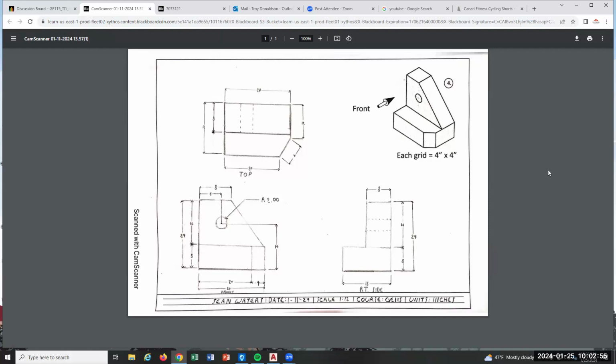How's it look? It's okay. It's got some dimensions around it. Is there anything wrong that you see here? It doesn't line up. What's that called again? I know, it's a big word. Starts with a P. Projection. Thank you. It's not in projection. So remember that the left side of the front view should line up with the left side of the top view. That's called projection. In AutoCAD, it's really going to help you.